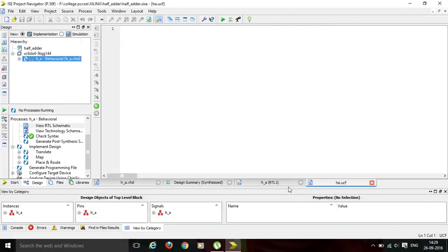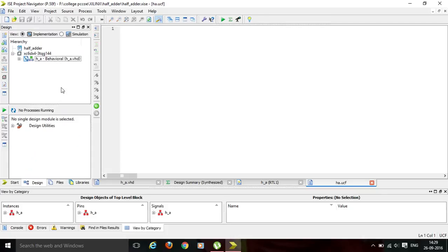Next, finish. So now a blank editable window would come up. The pins that you need to be mapped, you can very much make a mention on this UCF file. Once you write down the pin numbers, you can save that UCF. See, now inside your .vhdl file, that UCF file is visible. You can save the file, and then we are all set to move towards the final implementation.